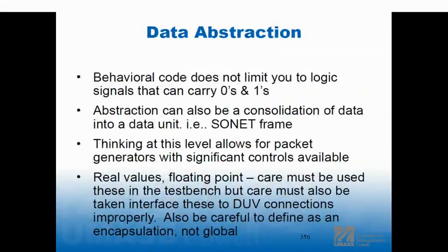Okay. Now that we put this wedge in between the DUT and the tasks, we've abstracted the data. You remember when I talked about math? Well, this is important for similar reasons, because we're describing what we want the BFM to do in human-like terms, in test case terms, but we have to know that it's coming out bitwise the way we want it, because that's what the bus functional model does. It translates from a high-level request to bits, the bits on the DUT.